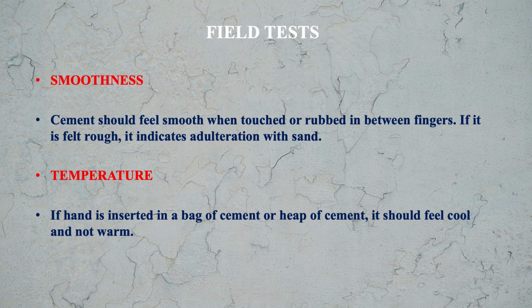Then we should check the temperature. If the hand is inserted in the bag of cement or the heap of cement, then you should feel cool and not warm, because warm means some moisture has gone into the cement and pre-hydration is there. Then only warmness will be felt.